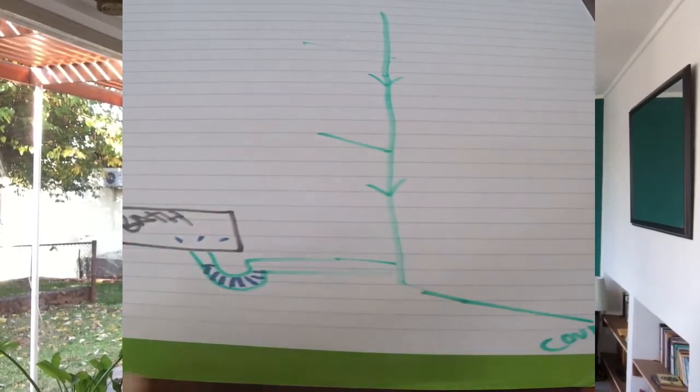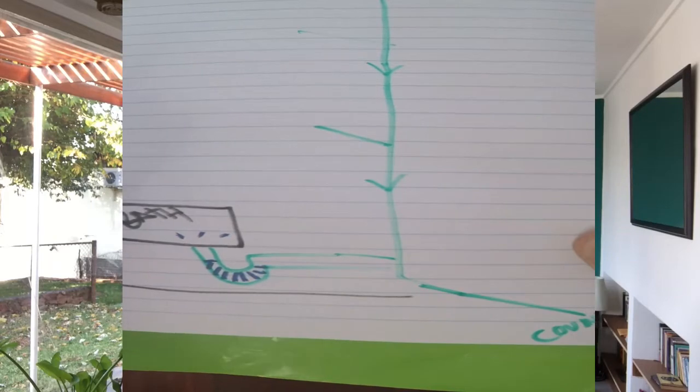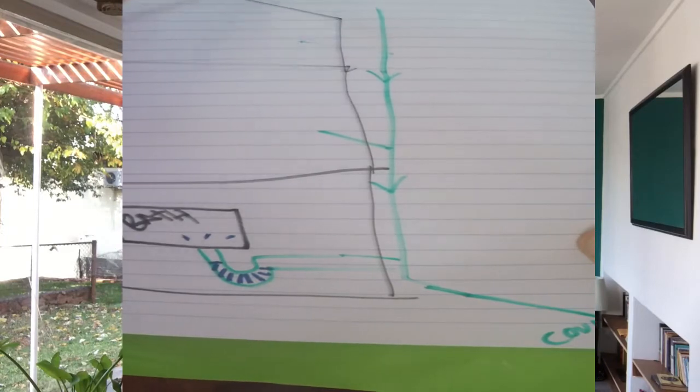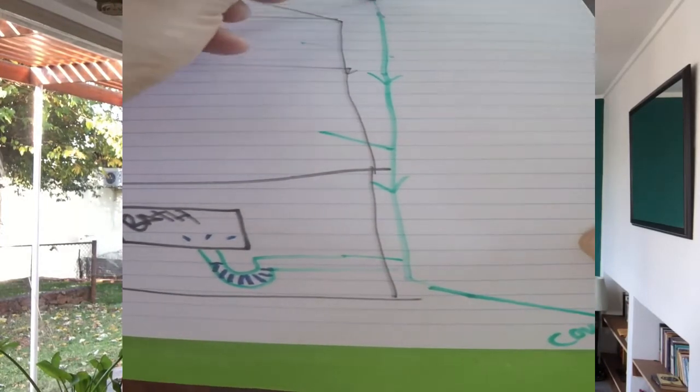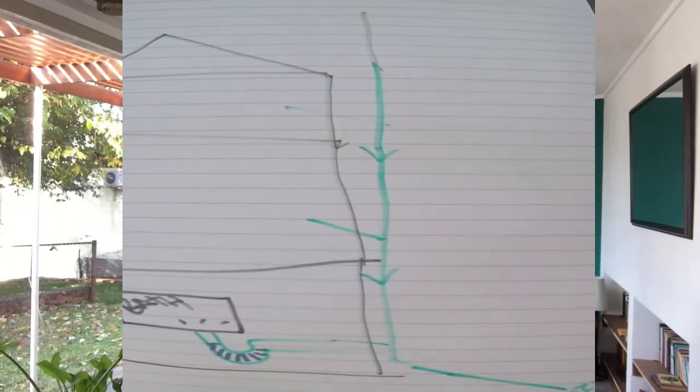The pipe work also needs to be vented. So if you see on most buildings, there's a vent that goes up out of the building, and that is to pull the air through and down and out. And so with your ventilation, when you pull the plug, if it's not vented correctly, your toilets will bubble up, or they won't drain fast enough, or they'll gurgle as they're draining. That shows that you have insufficient air in the system.